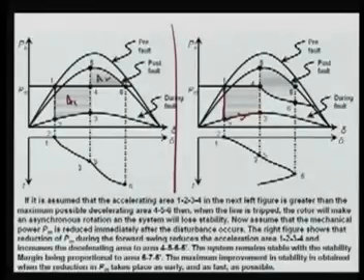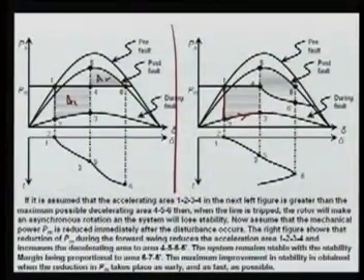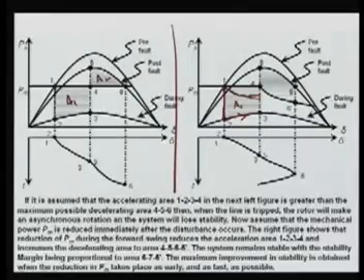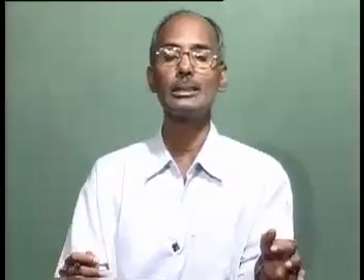Now again, if you can have a very fast action, you can change at this point when the fault has occurred, you can reduce this PM as well here. For example, you can reduce the PM. So what will happen, your oscillating area will be reduced, but this time is very, very fast and it may not be possible, let's suppose. But even though your fault is cleared at this point, during that period again we can reduce this PM. Then what will happen, we are increasing the de-oscillating area A2, and we are decreasing your oscillating area. So what is happening, we are improving the stability of the system.